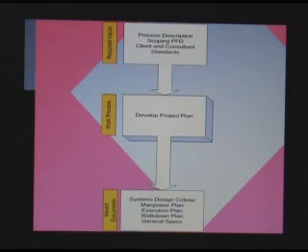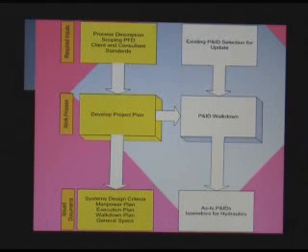So now P&IDs go through these development steps. First, develop the project plan. This is done by the leads in process, and they produce the design criteria for process, manpower plan, execution plan, walk-down plan, and general specifications. We will talk about these a little bit later. So what is P&ID walk-down? That'll be the next step.